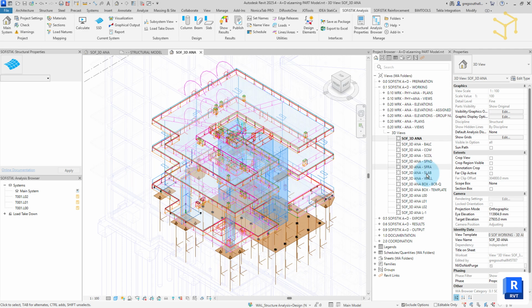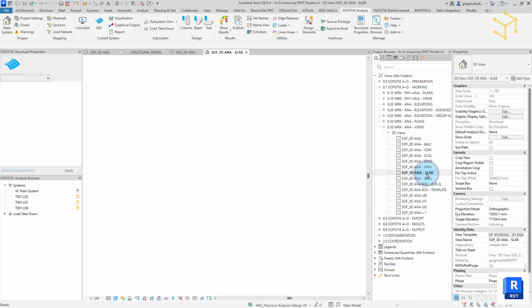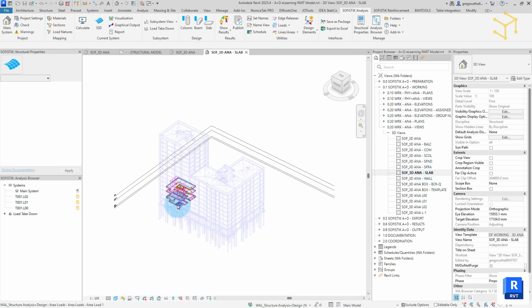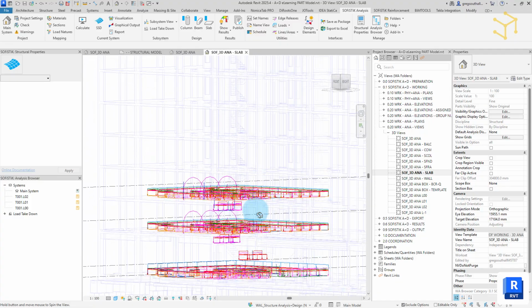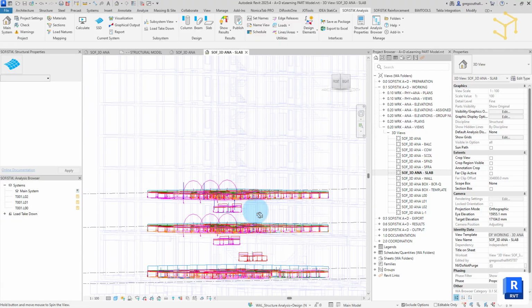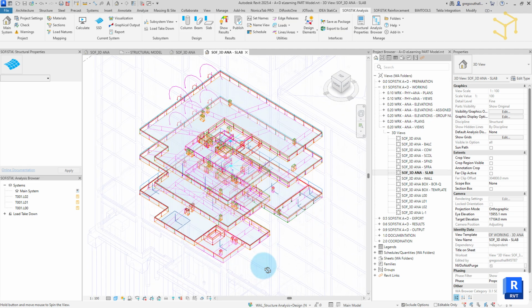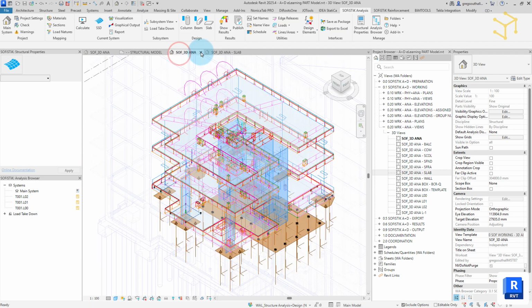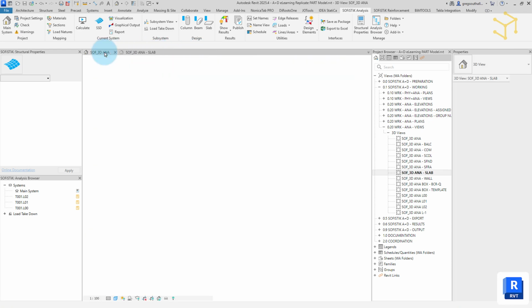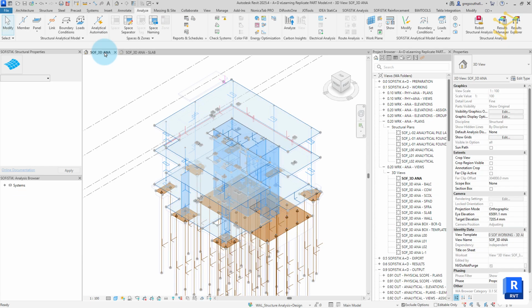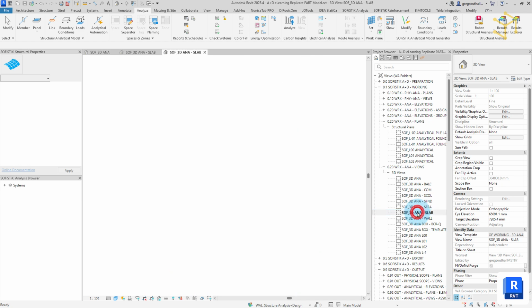As we generally apply gravity loads to slab elements, we can use the 3D Analytical Slab view to isolate for only these elements for an easier and cleaner exercise. We'll do the same for our in-progress model and first check our visibility filters are selected for loads in the view template.